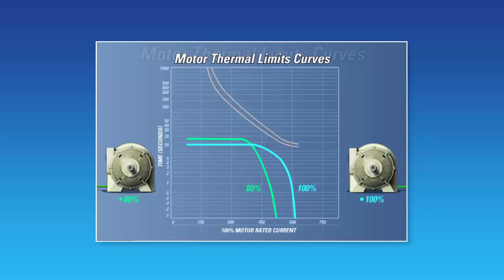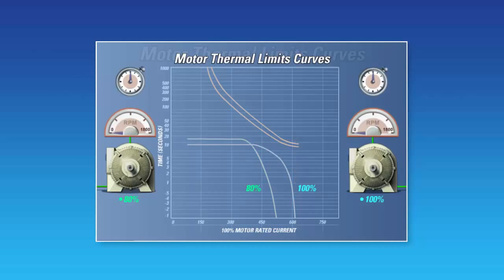As can be seen on the curve shown, since the voltage and current are lower, it takes longer for the motor to start. Therefore, starting the motor on a weak system can result in voltage depression, providing the same effect as a soft start. The maximum locked rotor stall time for both a hot and cold motor can be read directly from these curves.